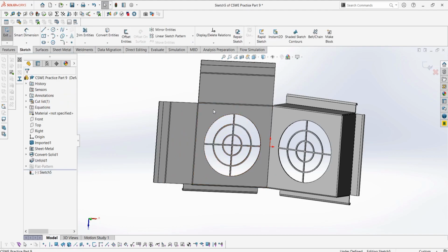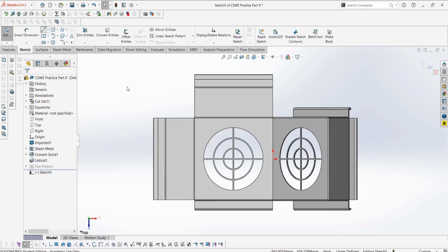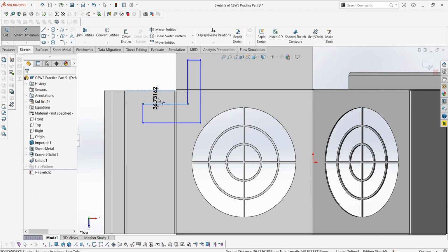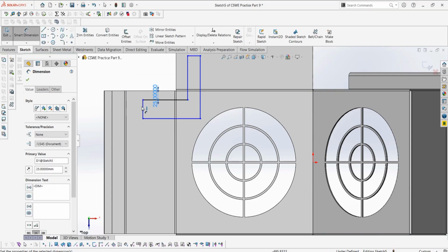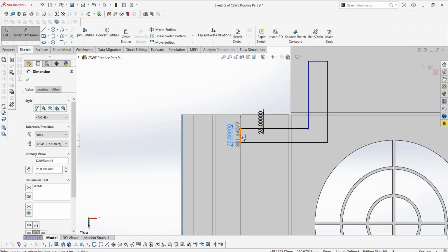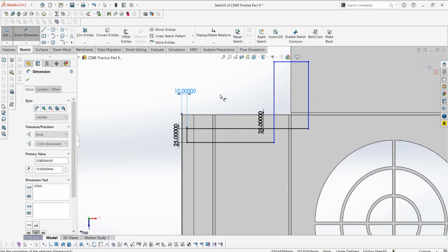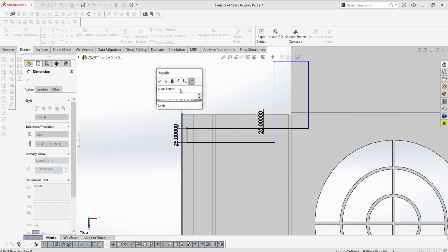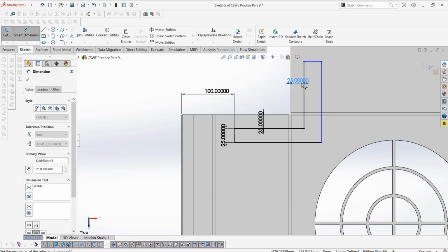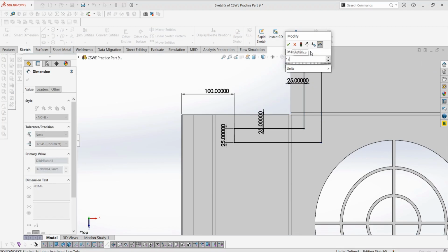make a sketch, dimension it all out. You can go back to the drawing. It's on GrabCAD, of course. I know the dimensions by heart because it's quite simple. It's a 25mm offset from this side, 25mm thick, 100 from the very end, and you're going to want to make sure you click the right line. 100. Oops, I put 10. Then 25 from here. 25, yet again.